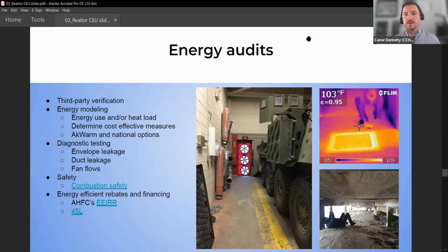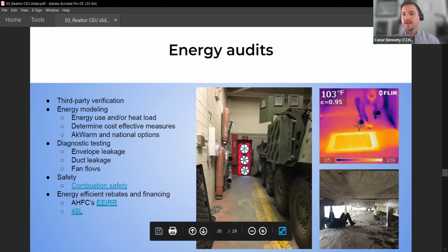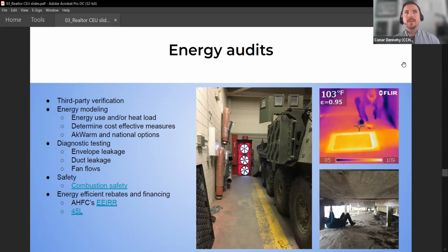So that's the walls, the roof, floor, doors, windows, anything that is between the interior and the exterior. And so once we've paired that air leakage, and they can take an infrared camera and they can really start to hone in on where there's conduction or air leakage happening, we can start to figure out a plan for how to solve the energy inefficiencies of the house.